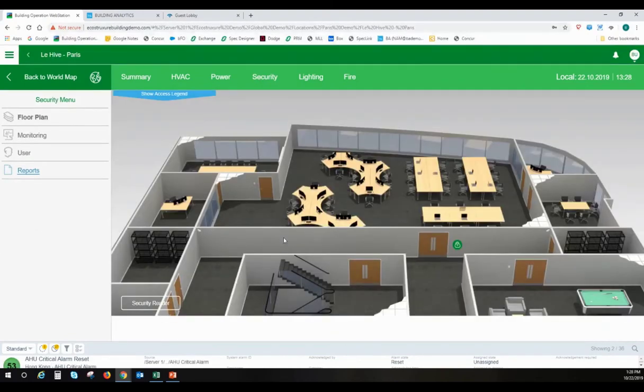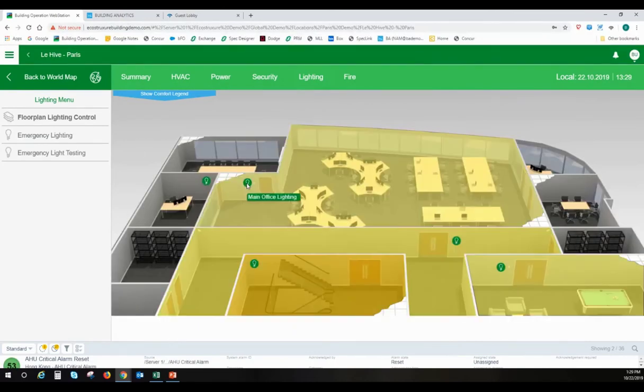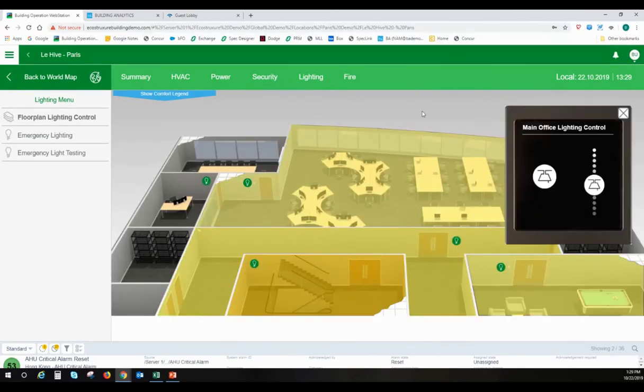And then if I get into security, and this is an example you saw already where I had the front door and I went ahead and unlocked the building, for example. I could do the same thing with a meeting room. So I can lock a meeting room, unlock a meeting room, have it turn on the lights, turn off the lights, have it occupied, unoccupied. And I can get into lighting control as well, to where I can get into actually controlling temperature in a space. And I'm going to let this drill down into that integration here.